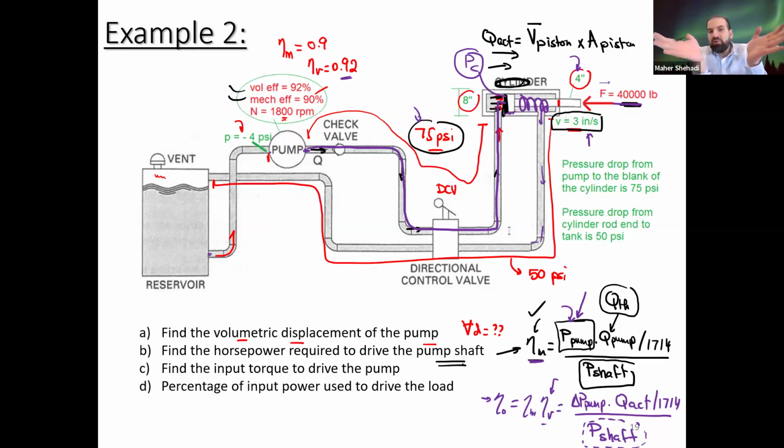Maybe there's some leakage somewhere in the system. So if you try to check the pressure drop created throughout the whole system and find the loss from that, which we can easily do as a power, just multiply by gamma and convert that to horsepower, maybe they wouldn't match between the input and the output. Hey, it's not matching. I only have delta P, where there are some other losses which you may not see. But basically, yes. If you can find a system with no loss, okay, that would be perfect. Okay, any other questions?